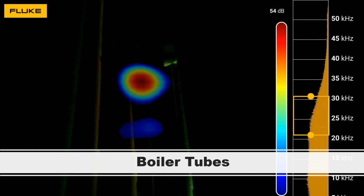Boiler tubes. If you don't have your air-fuel mixture proper on your boilers, it's not going to be running real efficiently. So understanding whether or not you're leaking air into the system, that's a real good thing to know. And once again, look on this. This is in a slightly different range than what was originally recommended. All right, this is giving you a little bit of the stuff right down in the high sonic and then the low ultrasonic.